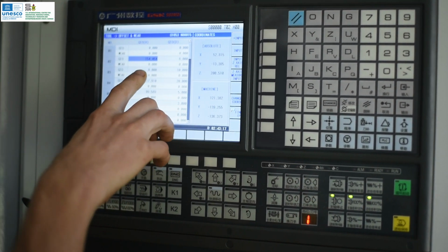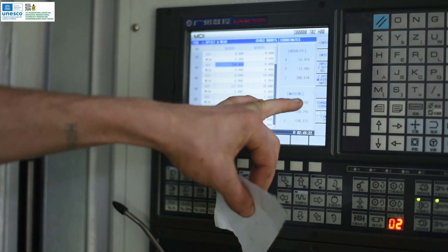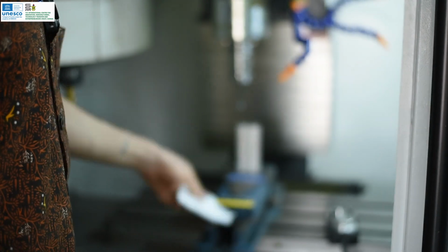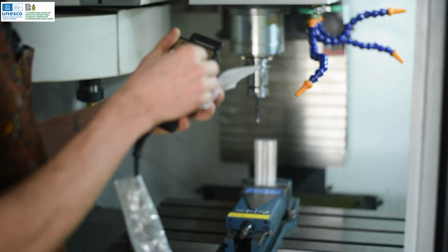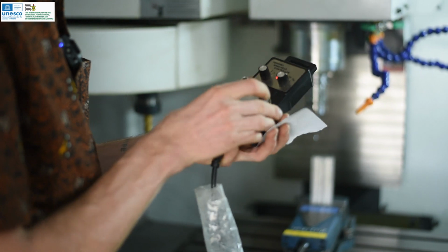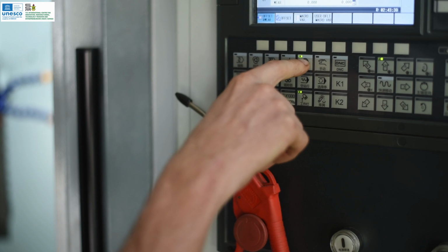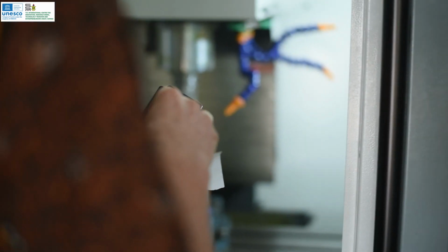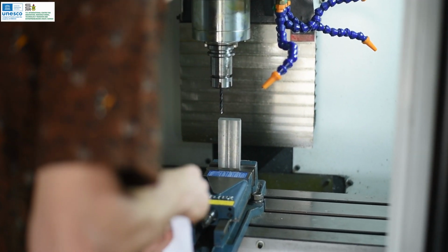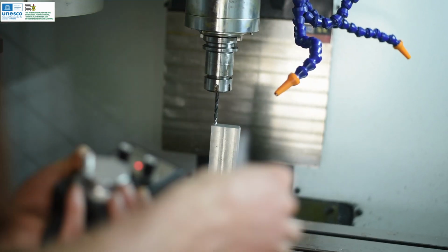For our length, we're going to measure in reference to what we had before. In this case, it's in reference to our position of the machine. So again, first things first, we're going to put it in 100 speed in our hand jog mode, or our pendant jog mode, and we're going to move down until we're close. Just like we did before, moving this down. We don't want to touch it, but get quite close.